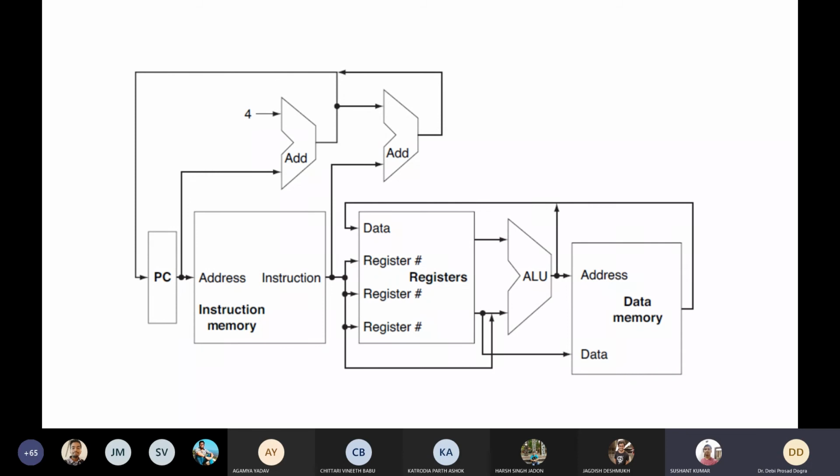So where you have written address after the operation of ALU, there can be data as well, right? Okay, no, we can directly store to registers, right? That's why it is going back and going to the data port of the register file. We don't need to store in data memory. Why would you need to store into the data memory? Then data goes directly here. You see that there is a data port here.